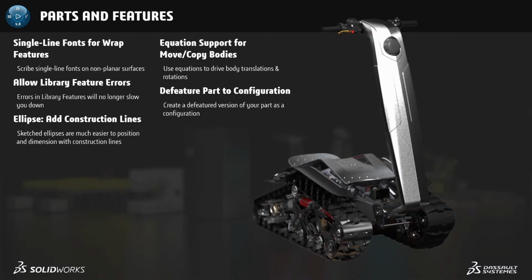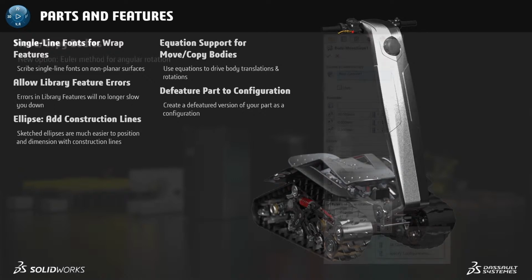So one thing that we didn't take a look at in that video there was just the defeature part to configuration. Just as I mentioned earlier, you can now create it as a configuration. So if you're not using defeature at all, it allows you to take a part that has a lot of complexity, such as if you are actually modeling in threads or anything, and you need that for maybe a print, you're able to create a defeatured configuration now and have that defeatured configuration in your assembly to increase your assembly performance. This was available. However, in the past, you had to create it as a separate part file, which was linked back to the original.